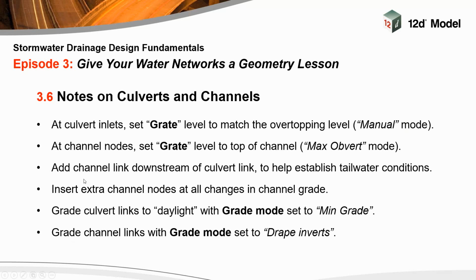It's a good idea here to add a channel link downstream of a culvert link for hydraulic reasons, to help establish a tailwater condition there, if it's otherwise a bit questionable what the tailwater level is.